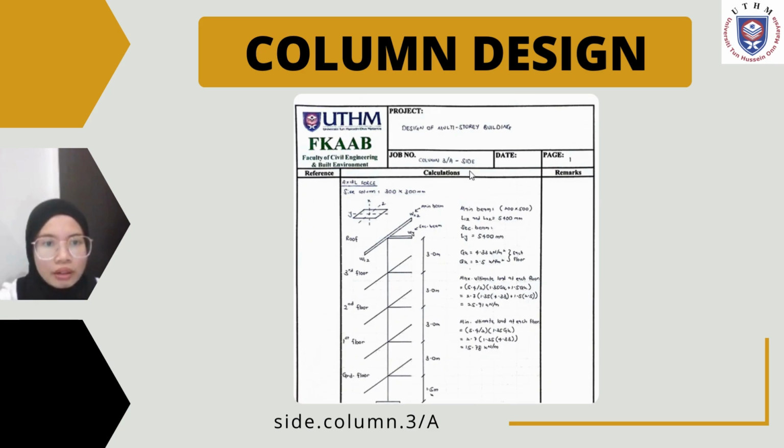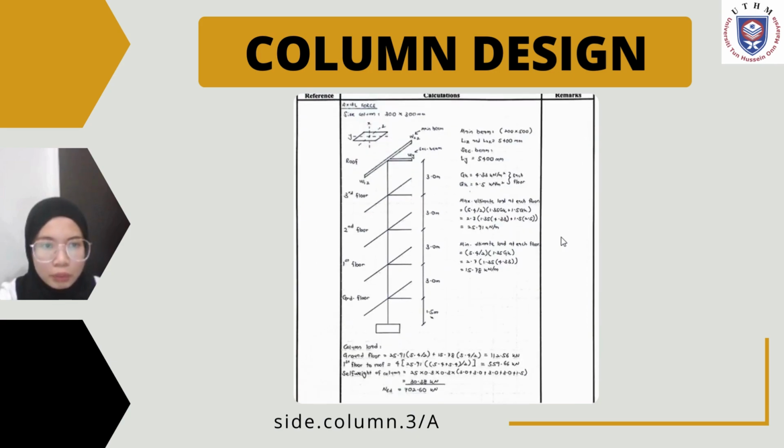To get the column detailing, we must know the value of axial force and moment, the specification that we already provided as shown in the body diagram. The size and length of the beam, size of column, GK and QK for each floor are also given.